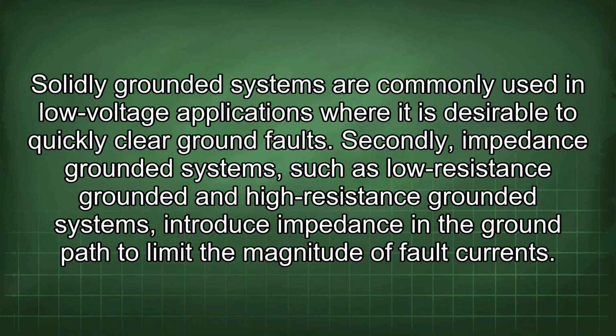Solidly grounded systems are commonly used in low voltage applications where it is desirable to quickly clear ground faults. Secondly, impedance grounded systems, such as low resistance grounded and high resistance grounded systems, introduce impedance in the ground path to limit the magnitude of fault currents.